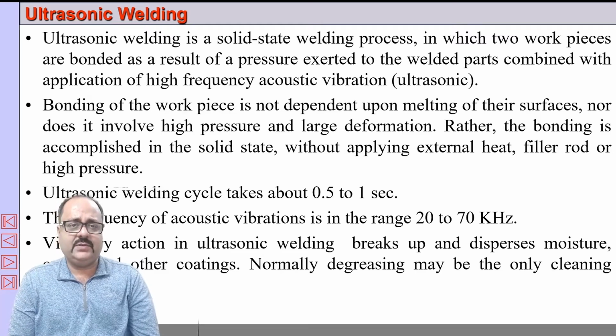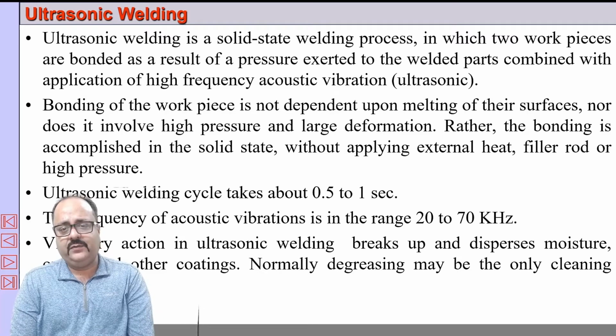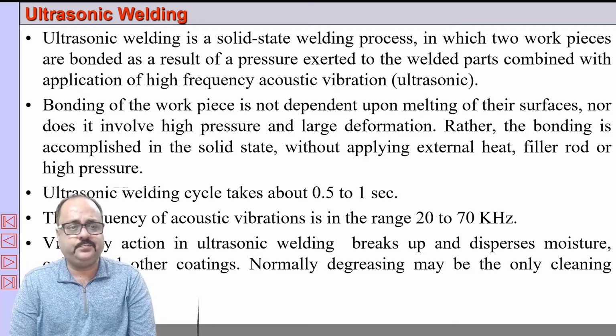Also, the welding time is very less. It can vary from 0.5 to 1 second or maybe less. So since there is no melting, it is carried out in solid state. It is called a solid state welding, and it is also, you can say, an autogeneous welding process. No additional filler material is added, no fluxes, no sealing gases, etc.